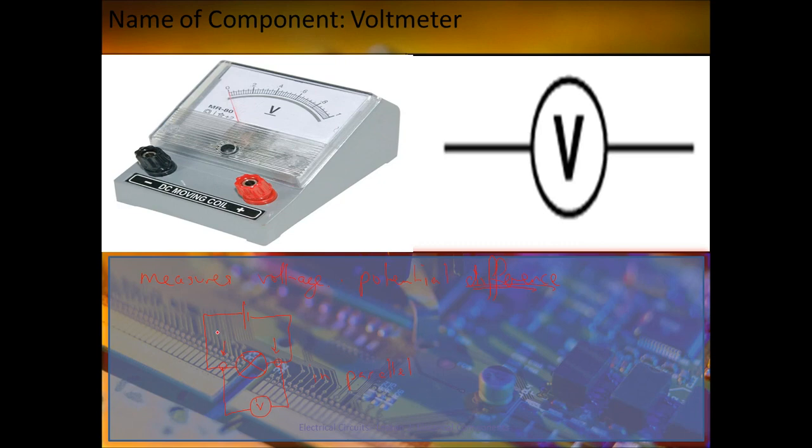So if you had electrons going in with 12 volts, and let's say we had another bulb over there, so it's not going to 0, and they come out the other side of that bulb with 3 volts, then the voltmeter would do that calculation for you. They started with 12, they end up with 3, so therefore 9 have been used up from the first point to the second point, and therefore the bulb must be receiving 9 volts. And obviously that last 3 volts would go to the other bulb, so the electrons use all their potential before going back to the battery.